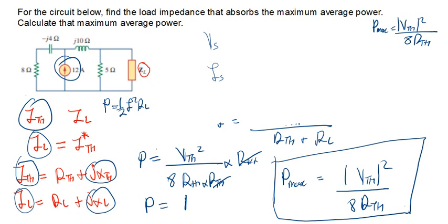So if I switch off my voltage source, what am I going to have? Is it a short circuit? Is it an open circuit? Keep in mind, if you switch off a voltage source, what you're going to have is a short circuit. It's just more like a line, just a wire. And for this one we say resistance is equal to 0.